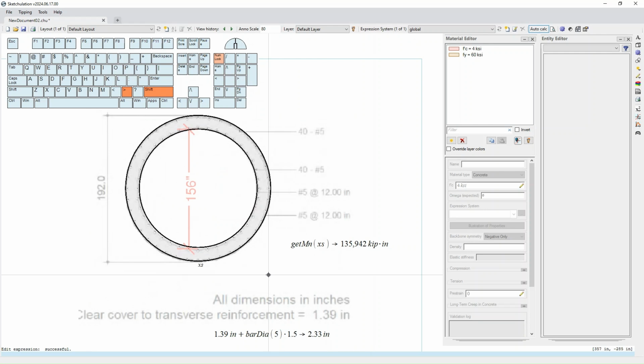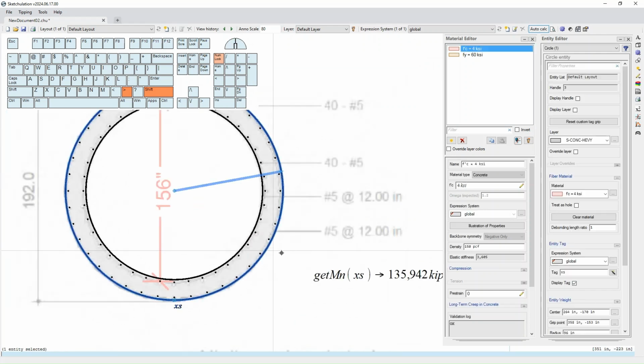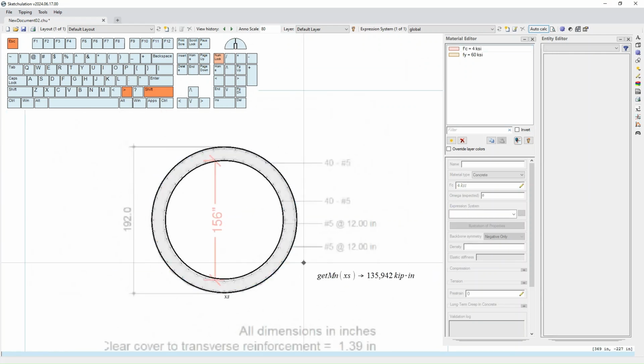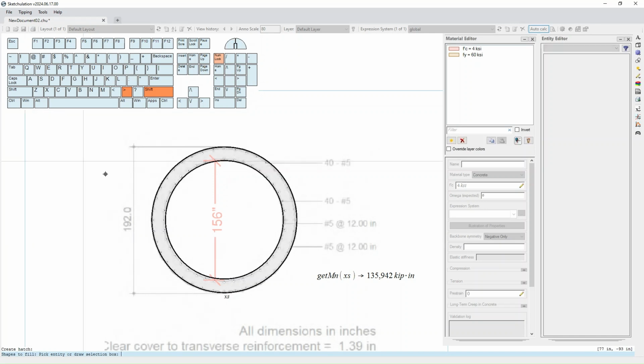Now I'll just go ahead and demonstrate. If I wanted to change this and show the hatch option, let me just show how that works quickly. First I would run the command. We want to do a hatch by boundary. First we want to select our hatch type. So we'd select concrete, select the outer shape, which is my fill, and then push enter, and then it's asking for holes. So then I select the inner shape, and we'll go ahead and delete the boundaries in this case.